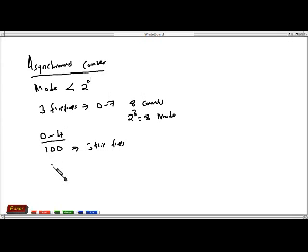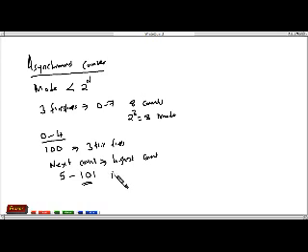For us to design a counter whose mod is less than 2 power n, we consider the next count after the highest count. Because we are counting from 0 to 4, our next count will be 5, and 5 in binary form is 1, 0, 1. So we will make use of the next count to reset our flip-flops.